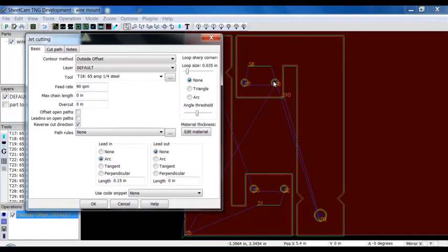It will allow you to slow down the cut for holes. On an inside corner, you could set it so that, say, a 1/4 inch before the corner, the machine slows down and turns the torch height control off, and then 1/10 of an inch after the corner, the machine speeds back up. All of that can be accomplished in the path rules.